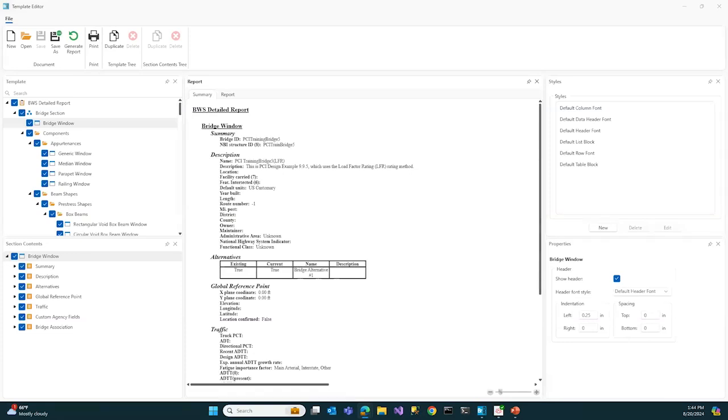You said there would be added functionality to the outputs. Our client requires multiple individual POIs for each member, therefore multiple member alternatives, and the tabular results to be printed for each. This results in dozens, if not hundreds, of individual runs per bridge. It'd be significant time savings and cost savings to be able to batch run and print the tabular results for multiple member alternatives, not just for existing and current POIs for each beam. Currently, for each alternative, we must run an analysis, go to tabular results, modify the display.